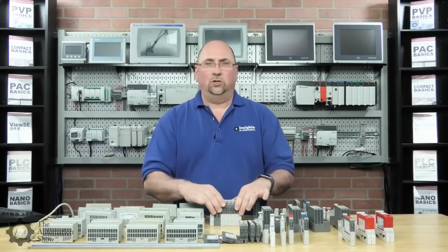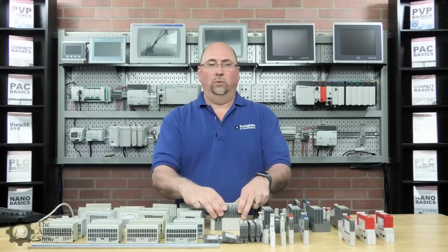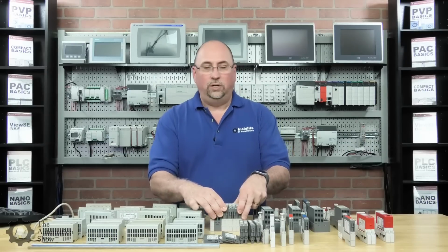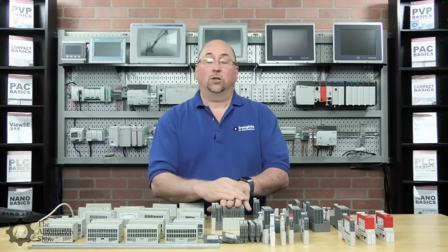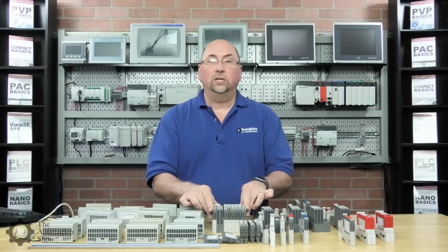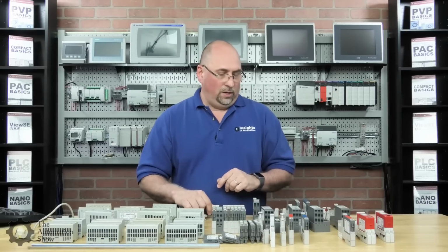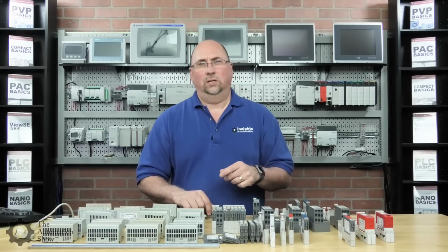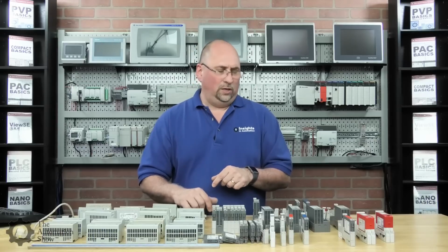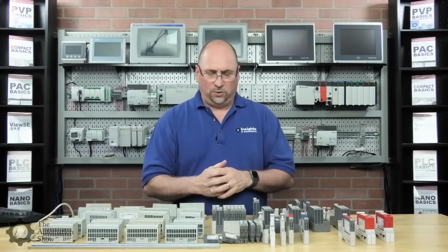But in any case, just know that point I/O, if you download to the controller, will not hold last state. It will go off. That is not an issue with FlexIO. So that's an important thing, not for most applications, but for some mission critical applications, it's something you really need to know. And I'll even put a link to the tech note in the description in the show notes for this episode. So if you're interested in that, you can find out about that.